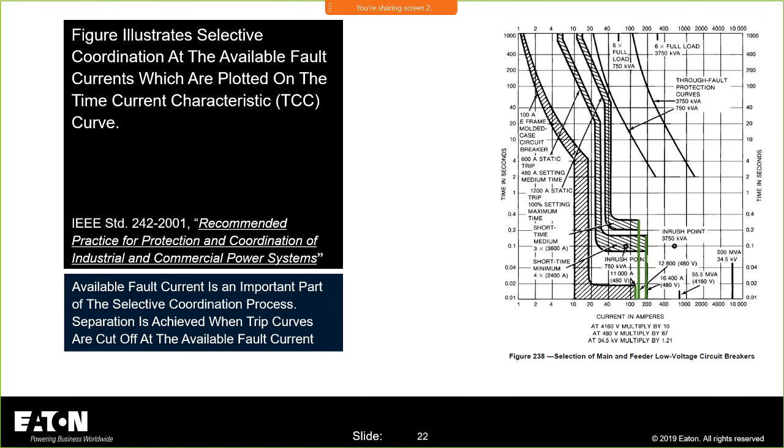But suffice it to say, all of these breakers may not be at the same voltage level. Some may be on the primary of that transformer at a different voltage level. So there may be two different transformers in the picture as well. So there may be two different levels of voltage, and we have to put those all together so we will reflect these curves from one side of the transformer to the other. And that is a part of one of the questions that we had in the quiz, which we're going to talk about: the impact of a transformer on the time current characteristic curves.